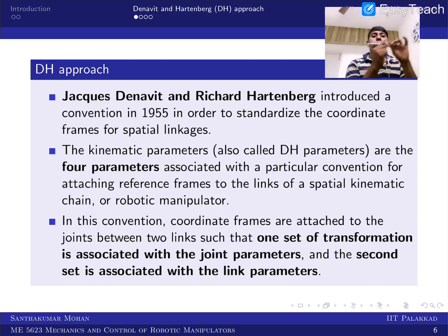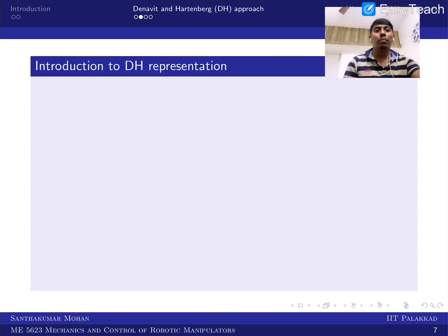So now this particular link would be associated with the link parameters. In the sense, the joint to joint information I can deliver with the help of one simple set called the link parameter set. So this is what Denavit-Hartenberg have done. Further, they made some simplifications, and that is what we are going to see in this lecture.